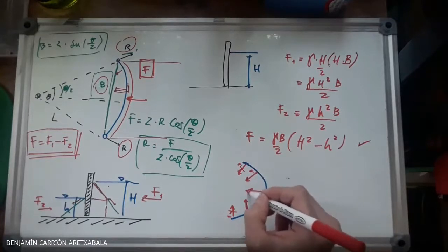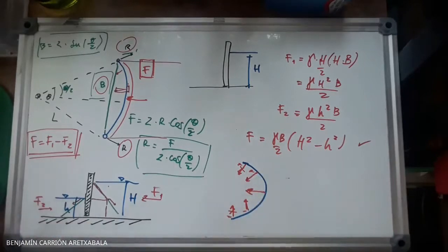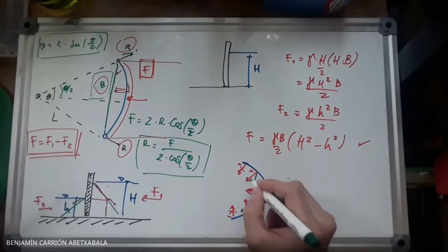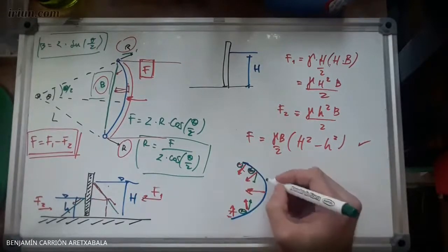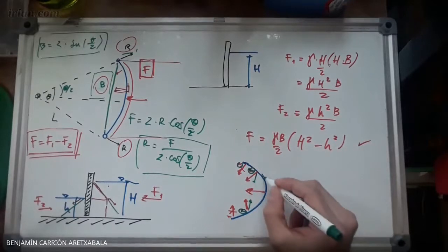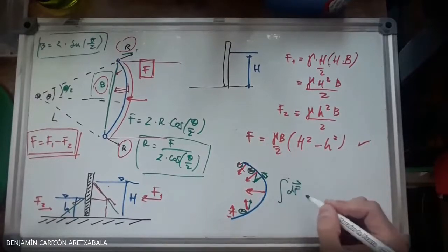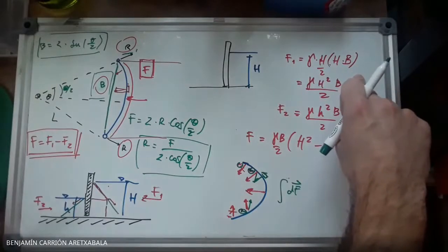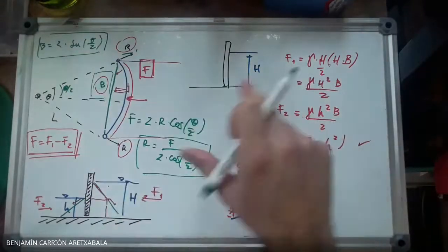Of course, this adds totally, but the vertical component of this piece cancels out with this one, and you only end up adding this one. And if you do the integration, I mean, you can do this. If you go and actually integrate the delta force acting on each of these pieces, but treating force as a vector, you're going to end up with this very same equation. So the only important area is going to be the projected area.